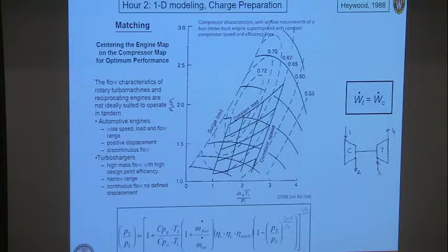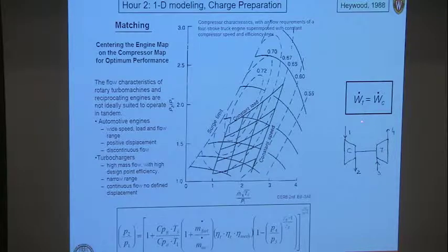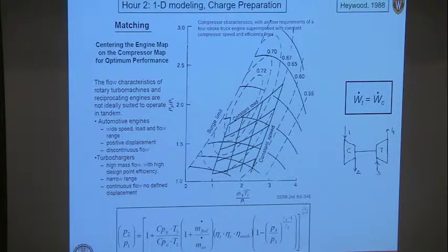So how do I actually calculate in a model the relationship between the exhaust pressure and the inlet pressure for a given turbine arrangement? Well, we know that the turbine work and the compressor work must be equal. So if I look at it this way, my compressor goes from state 1, my atmospheric state, to the boosted inlet to my engine, state 2. The exhaust from the engine is state 3, goes across the turbine, and is exhausted to atmosphere at state 4.